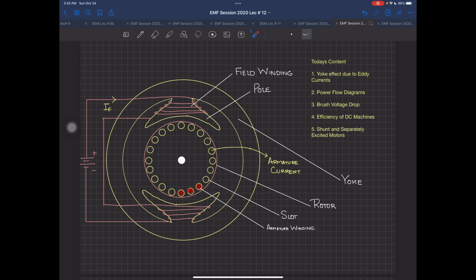But normally, whenever a DC machine is being used in the industry, the source is a DC source. But whenever you want to change the speed of the DC machine, you have 2 or 3 different methods, and we will be discussing them in the next lecture, speed control. But since we have done an experiment in the lab related to armature voltage control and field winding control, those supplies which are controlling the applied voltage to the field winding or the armature winding are PWM based, or they are based on some semiconductor switches, maybe a transistor, MOSFET, or something like that.